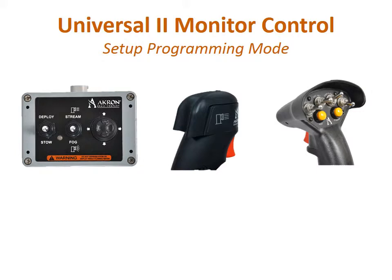Starting with system power off, setup mode is entered by pressing and holding the stream switch on a connected control device. This can be a toggle switch, rocker switch, or a push button depending on the device being used. After the switch is pressed and held in the stream position, apply system power and continue to hold the stream switch for approximately 3 seconds.